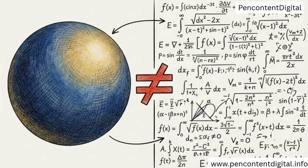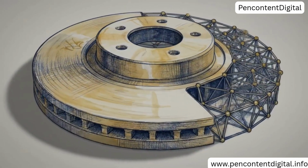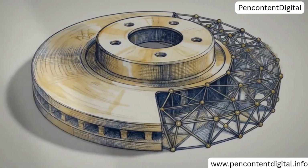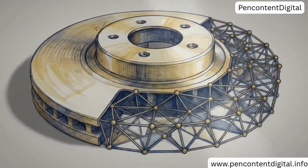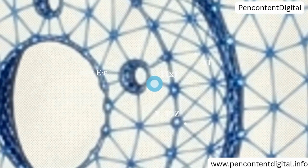Step 4 is generating the mesh. Computers cannot easily solve complex physics equations across a single, continuous organic shape. To solve this, we use discretization, the process of breaking the continuous model into thousands of smaller, calculable geometric elements. Within this mesh, the software solves the physics equations at specific points, called nodes, where these geometric elements intersect.